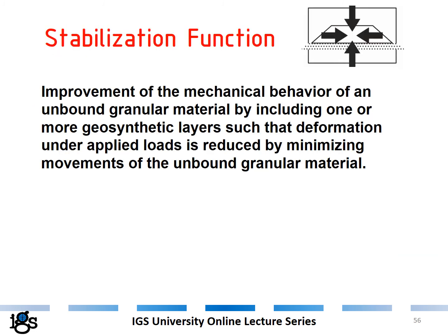The last function I would like to discuss is the stabilization function. It's defined as improvement of the mechanical behavior of an unbound granular material by including one or more geosynthetic layers such that deformation under applied loads is reduced by minimizing movements of the unbound granular material.